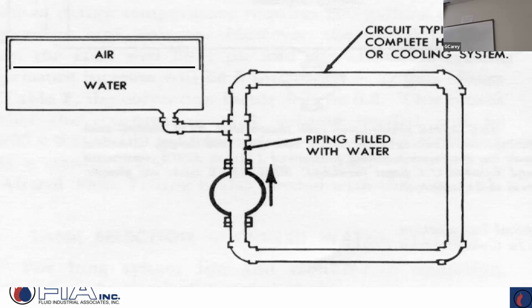If I heat the water, I'm going to change the pressure because I've added water. If I open a feed valve and add additional water to the system, I'm changing the volume. I'm going to change the volume of air. But if I don't have those two things going on, I simply turn a pump on, I can't change the volume of water. I can't change the volume of air. I can't change the pressure of the tank.